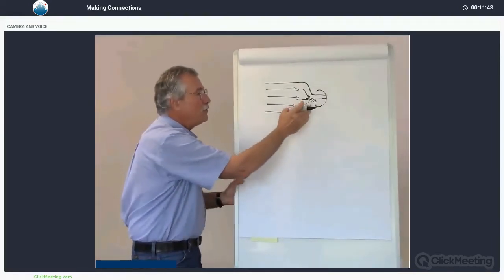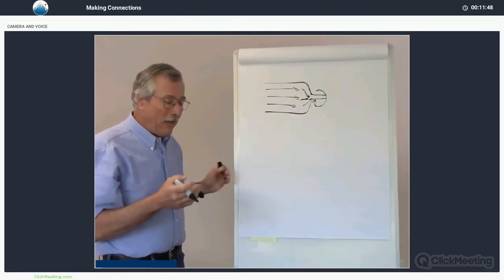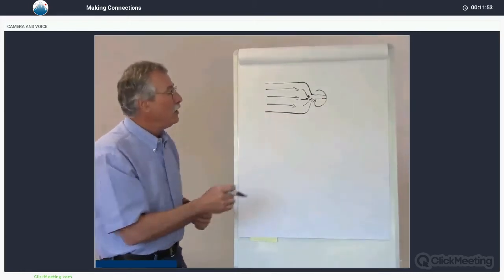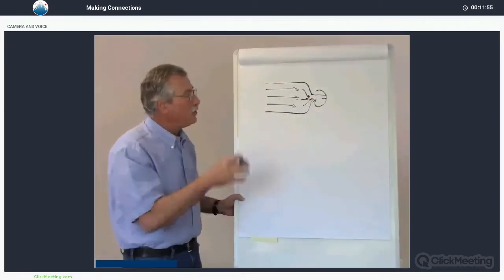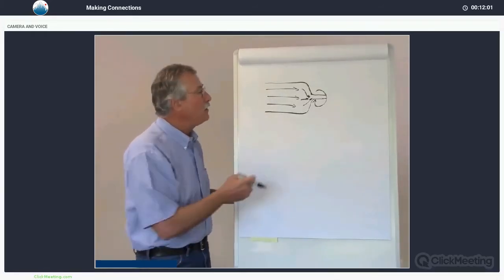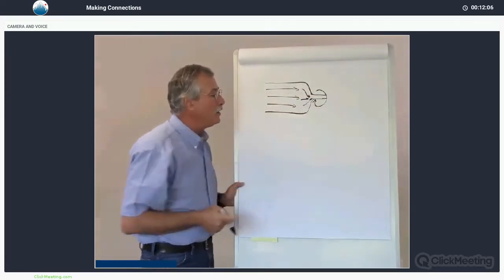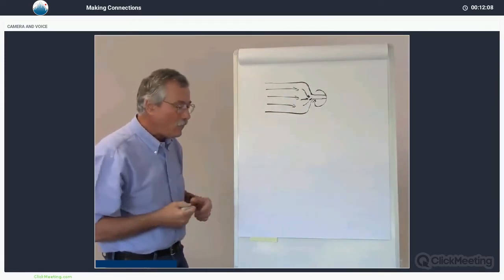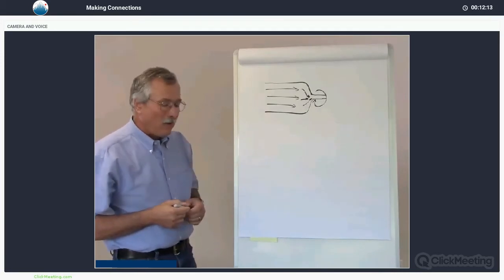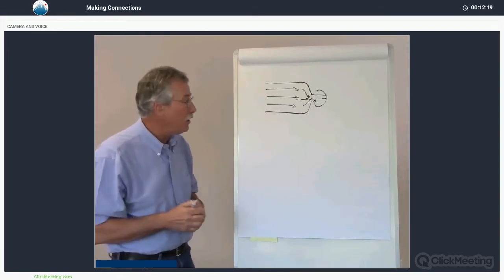Why do I mention this? Because sometimes folks are inclined to use a current probe to look at the output pulse. And a current probe won't fit over a nice big wide flat cable like we should be using, so they may attach a short wire in order to fit the current probe over that. Well, you've just created an inductor. And in fact, anytime you neck down the area of a wide surface, you are creating an inductance. So one of the issues that we have is folks trying homemade remedies that don't involve reducing the inductance, which is really the key here.